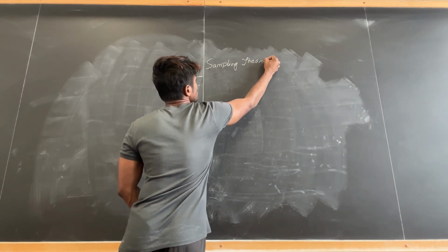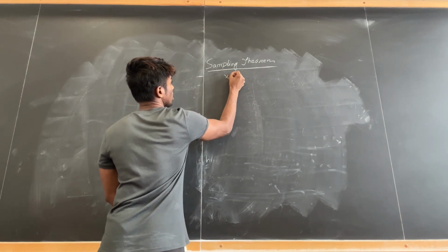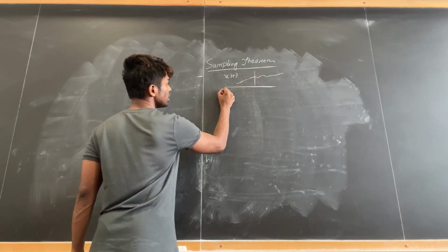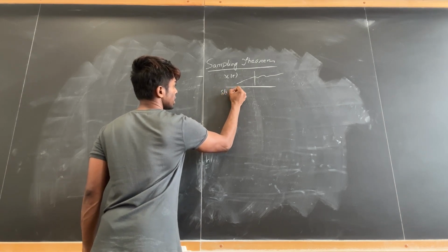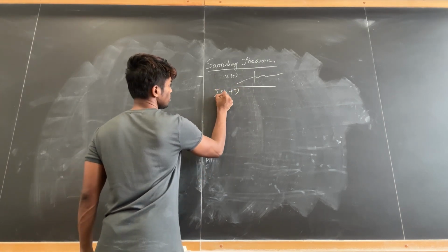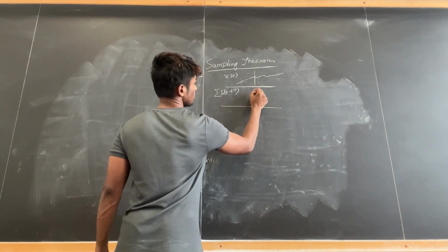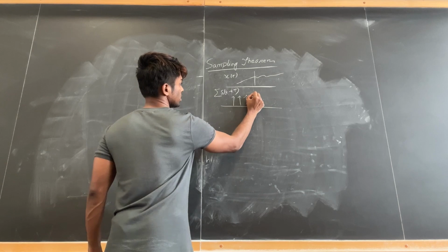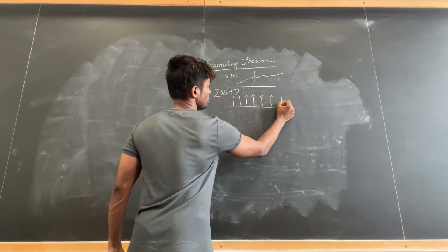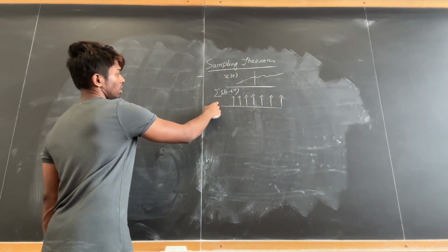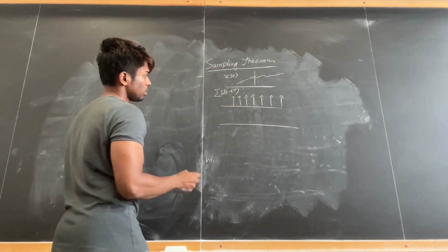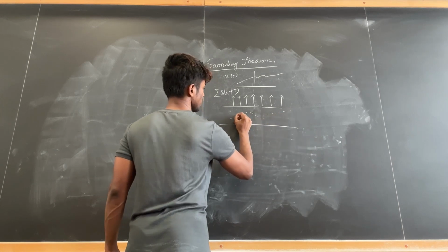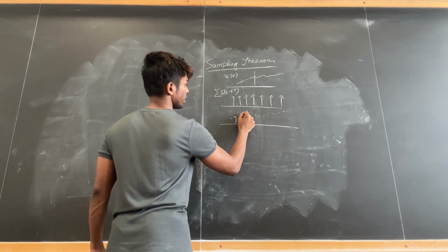We take a continuous time signal x(t), and this is any signal something like this. Then we take an impulse train, the summation of delta(t minus kT). That means it's some train of impulses. And we multiply the signal with this impulse train to obtain a sampled signal, and that gives us, in the signal's definition space, the impulses settled like this.